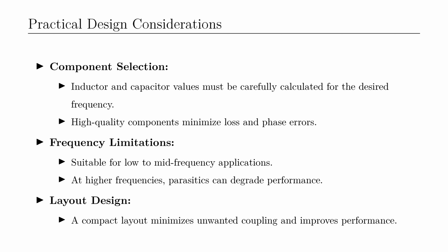Practical design considerations for the lumped-element balun include: component selection: inductor and capacitor values must be carefully calculated based on the operating frequency. High-quality components help minimize losses and reduce phase errors. Frequency limitations: the balun is suitable for low to mid-frequency applications. At higher frequencies, parasitic effects can degrade performance. Layout design: a compact layout reduces unwanted coupling and enhances performance.